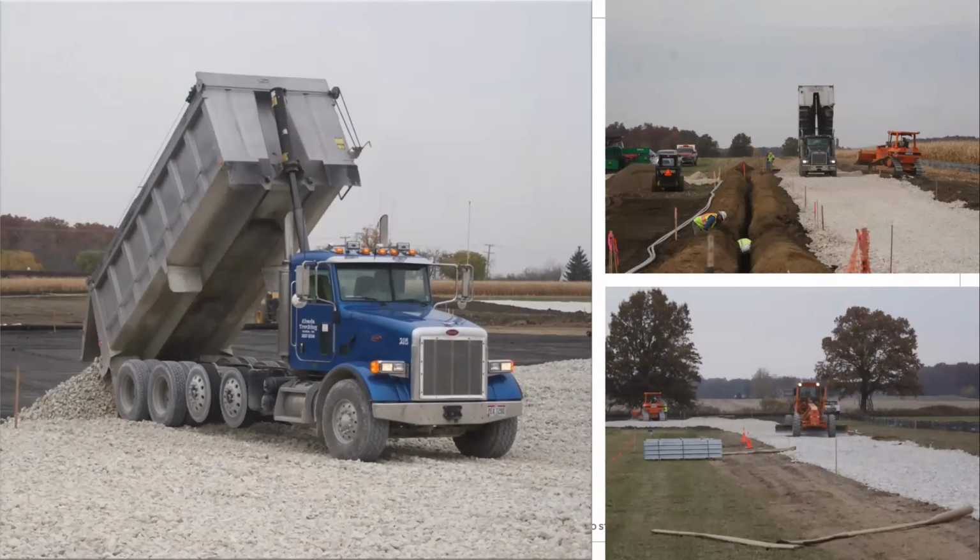Here's just another picture where you can see the access road being made. They're hauling in a lot of stone. On the left, there's one of the laydown yards that they're working on. Again, bringing that stone in, you can see a trench that's following the one access road. That laydown yard, once the construction was complete, that stone was removed and they seeded that area. There were no modules there, but it was returned to a vegetative state, I guess, once the construction phase was done.